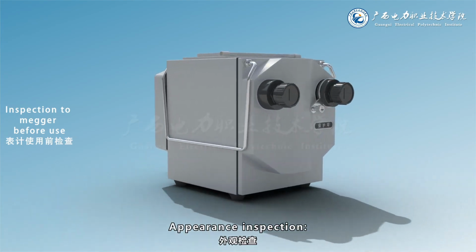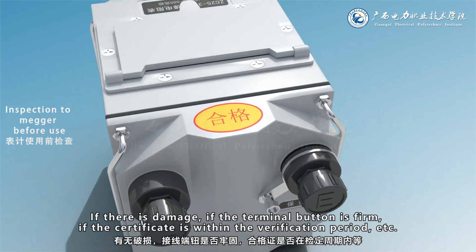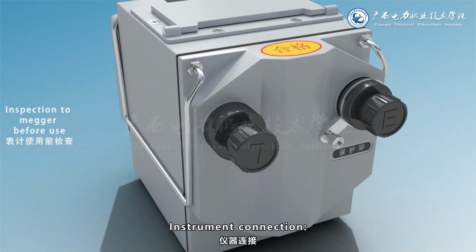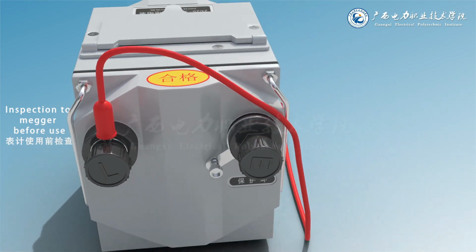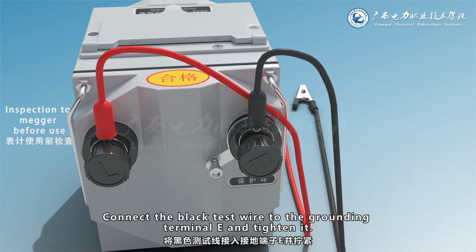Appearance inspection. Check if there is damage, if the terminal button is firm, if the certificate is within the verification period, etc. Instrument connection. Connect the red test line to the line terminal L and tighten it. Connect the black test wire to the grounding terminal E and tighten it.